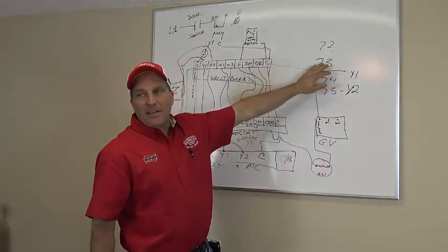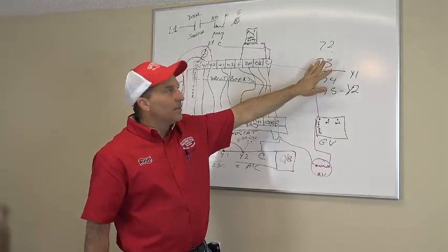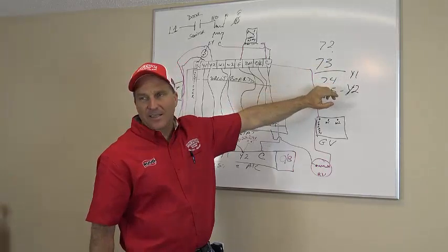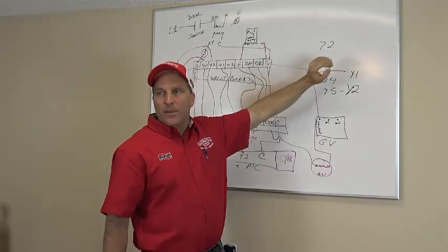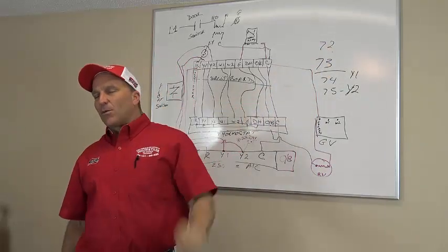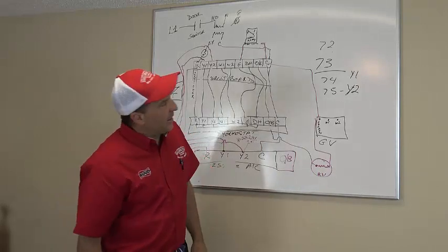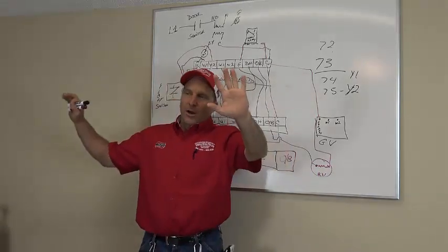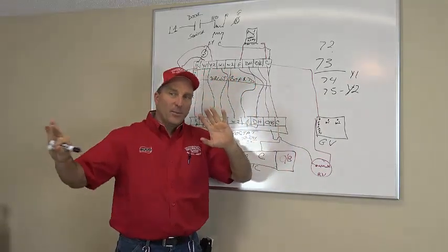It reaches 73. First stage kicks in, right? Can't handle it. Goes to 74. Second stage kicks in, right? Cools back down to 72. Thermostat is set at 50% relative humidity. It's going to go 3 degrees less. It's going to say, hey, wait. Don't shut off. Don't shut off. Stop. Don't shut off. Air conditioner, keep running.